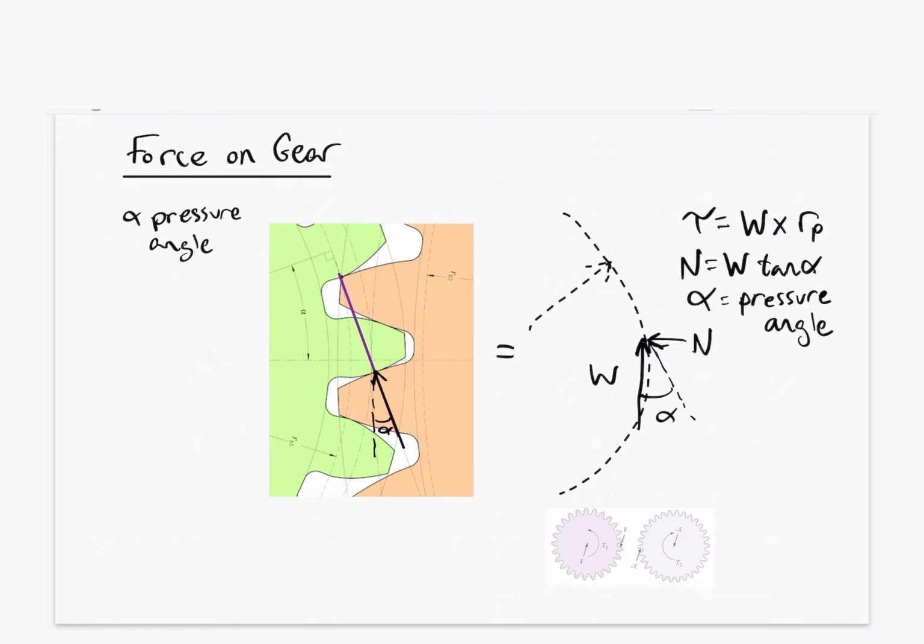And we often don't deal with F. So if we wanted to label this as our F, which we see in the book, here we have F and minus F as it occurs on our gear. But it can be important to know. So we can say that F is just going to be the square root of W squared plus N squared.